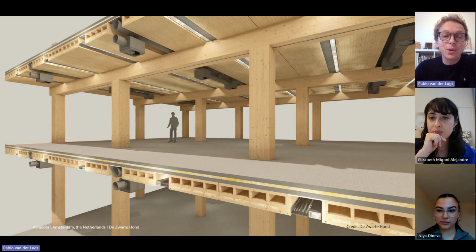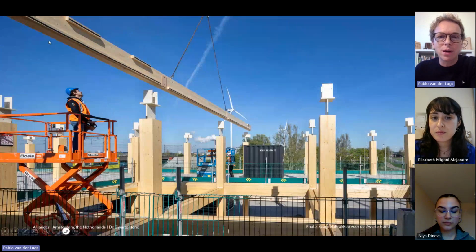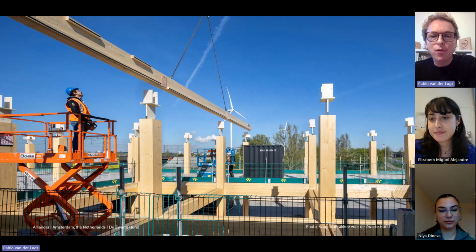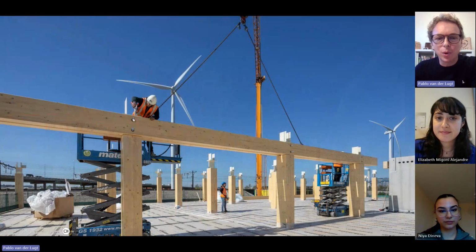And then next to that, it's also really built in a demountable way. So this is the sketch that the designer thought of in the beginning, right? And you also see that the climate installations are separated from the main timber construction. And if you look at the building site, you see all these large elements, and you see here that very smart, well, in this case, steel connections were designed, but for dismountability. So these long beams click more or less in these seams. They are then bolted or screwed to attach them.